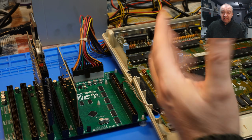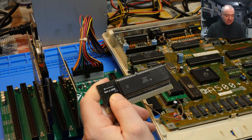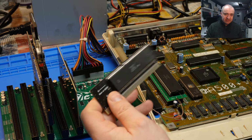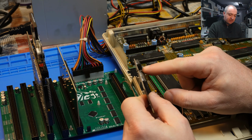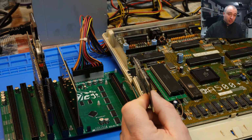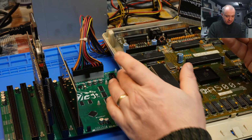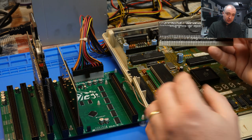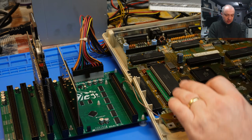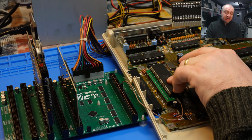And then for the coprocessor itself, let's just use another 68K because that's all I've got. Although we will be modifying this one ever so slightly, as you can see it's modified, as it has this jumper block on it. That's sitting on the E clock signal. In this setup, BOSS will be asserted low by this thing, just that wire there ties BOSS to ground. But with BOSS low, this CPU is tri-stated. Mostly, it's still generating an E clock.